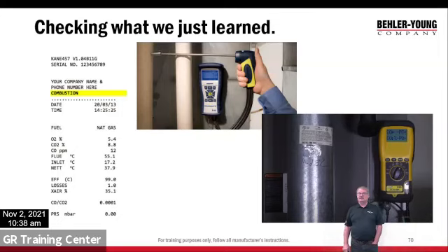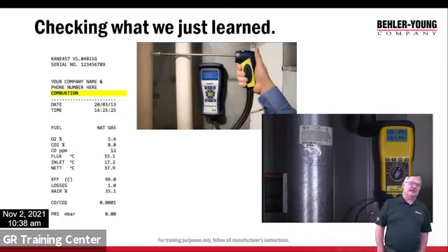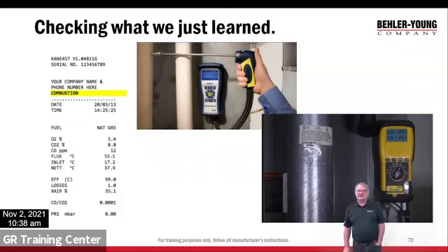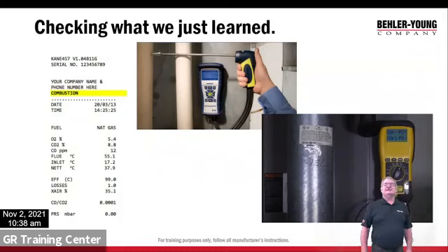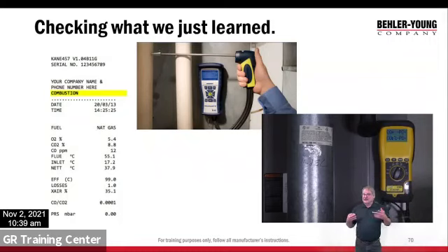All right, so on a good running furnace, that's a decent number. Obviously, the lower the number, the better. Flue gas, that's Celsius, 55 degrees. Inlet, 17 degrees. But let's go down to efficiency. It says that furnace is running at 99% efficiency. Wow. So for that cubic foot of natural gas that we paid for, I'm getting 99% of that heat in the house. Okay, so that's all the things that this combustion analysis tells us, again, from all the stuff we just looked at.